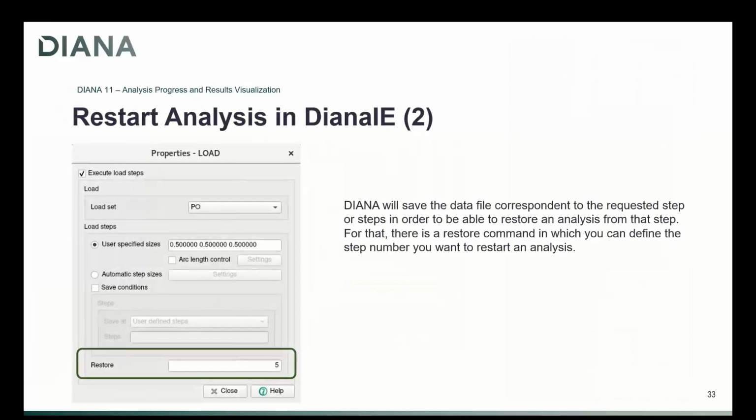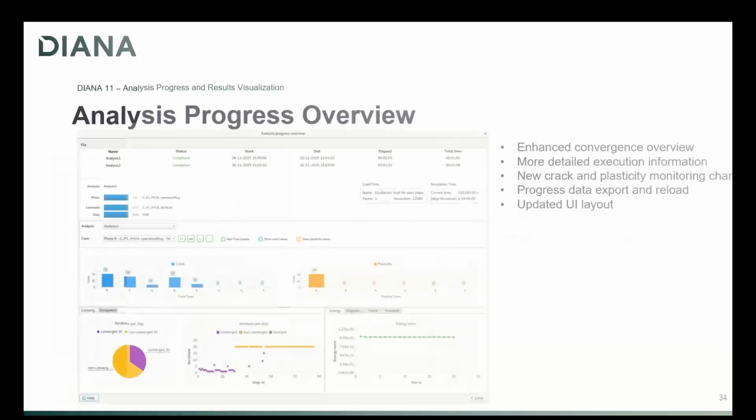Next slide. So in this next slide, I point out the restore. You can restart an analysis from a given step, and here is the command to do so. It is the restore command, in which you can define the step number you want to restart an analysis from. There is also a new tutorial that exemplifies how this is done now through Diana IE. Next slide, please.